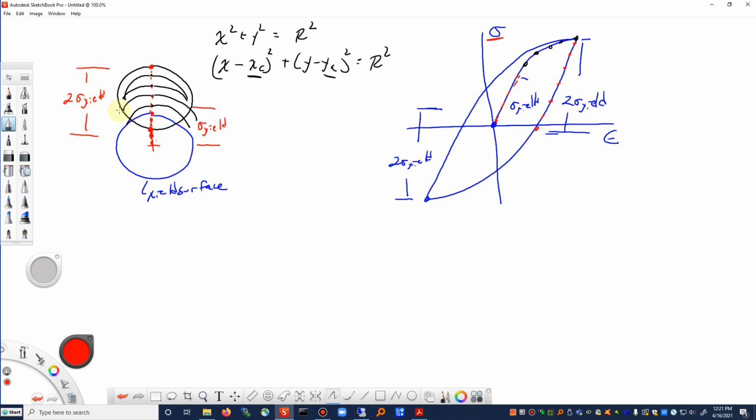Okay, so that's how we can get a similar behavior in the multi-axial sense from the uniaxial sense. The multi-axial behavior has to reduce down to what we observe in the uniaxial case. Once we hit the other side of the yield surface, then again, think of that washer or ring with your pin having been up here. It doesn't move. Your pin hits this side of the ring, and then as you move it further and further this way, that ring gets dragged, and now your new yield surface location maybe is down here.